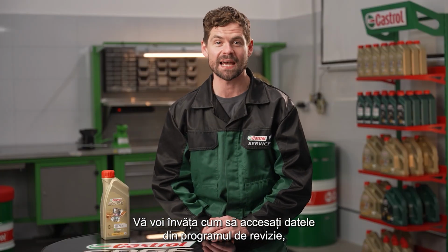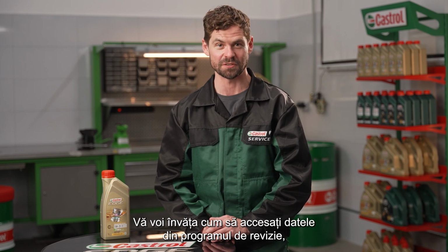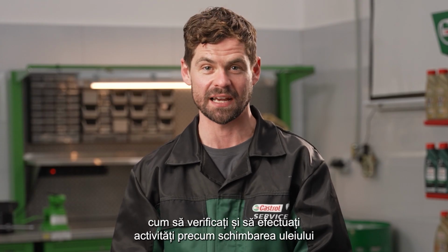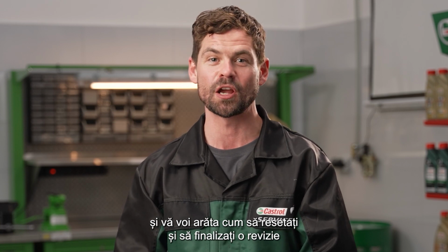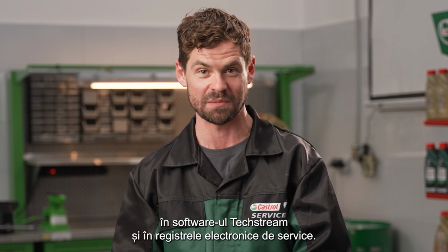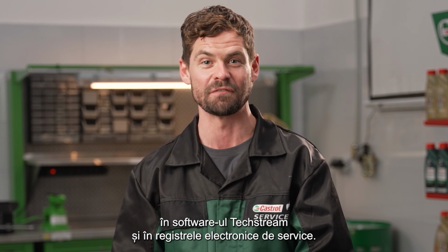I will teach you how to access the data on the inspection schedule, how to check and carry out the maintenance activities, such as an oil change, and I'll show you how to reset and complete an inspection in the TechStream software and the electronic service records.